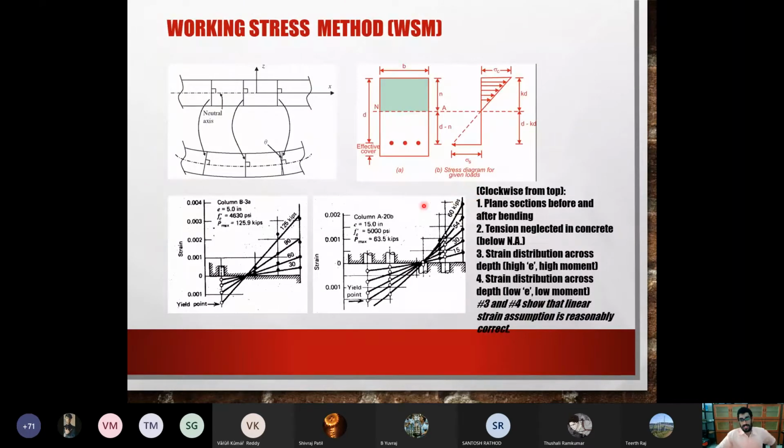Now, as I told you before, you see over here this assumption of plane sections. So, mechanics of solids, Euler-Bernoulli beam theory. What is the first assumption that is made? Beam bending theory, mechanics of solids. It's purely elastic. Okay, that's one thing. Then the bending will be part of a circle, like a curve, like the exact curve.